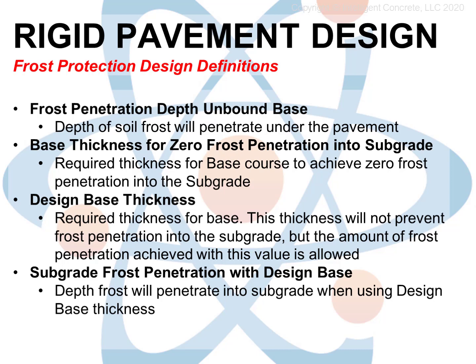If we want all frost penetration into the soil to be confined to the layers of concrete, base, and subbase, we have to calculate and build this thickness of frost-resistant soil. Why this is important is that constructed structural layers of base and subbase end up with far fewer voids, meaning, of course, that frost can penetrate into them, but because the voids are far less, there is much less space for water to occupy. And with less water, there will be less overall heave or expansion as the water freezes.